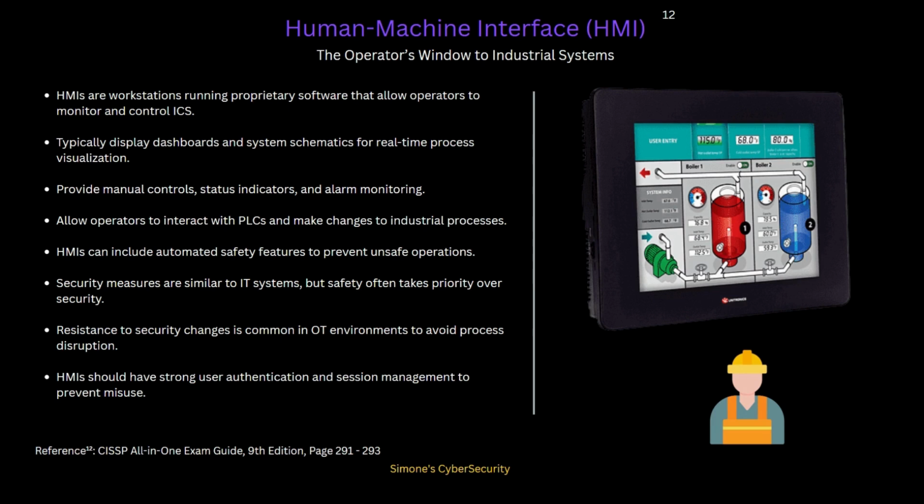Imagine if you have enforced strong authentication and unique credentials for each user, each operator who will be standing on the HMI, managing the control using the HMI. Imagine if an emergency occurs, but this logged in user has stepped away on a break and the HMI is locked due to a security control. Then the consequences could be severe, right?